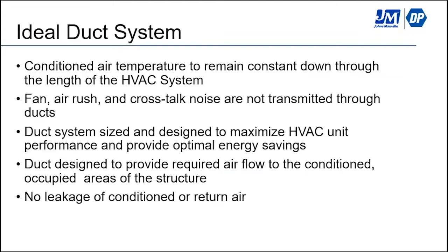You want to make sure that your duct is designed to provide the required airflow to those occupied spaces. And last but not least, and probably one of the most important things with a duct system, is minimizing leakage, or making sure no conditioned air or return air is lost.